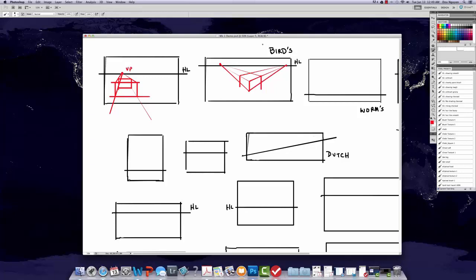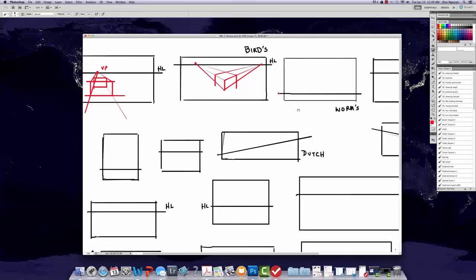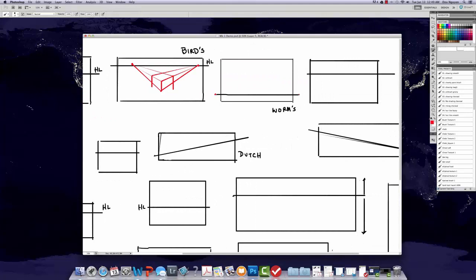Three-point perspective is like 2-point perspective, but there are no undistorted lines now. All the vertical lines now converge at a third vanishing point, either above or below the horizon line. If it's above, then we're looking up at the scene in a worm's eye view. If it's below, then we're looking down on the scene in a bird's eye view. Generally, the placement of the third vanishing point is used to reinforce the bird's eye or worm's eye.